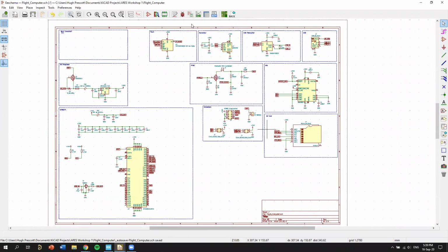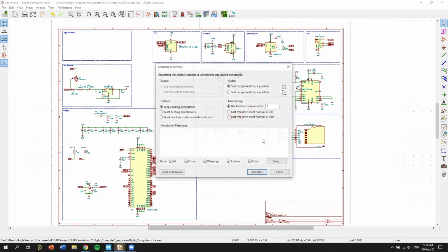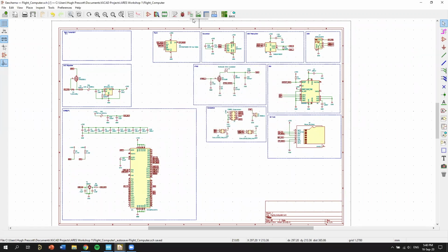So, all right. Here's the frightening bit. The first thing, if you remember, that we have to do after we have our schematic is assign our footprints. Oh, and before we assign our footprints, we have to annotate it. This just gives a little value to everything.